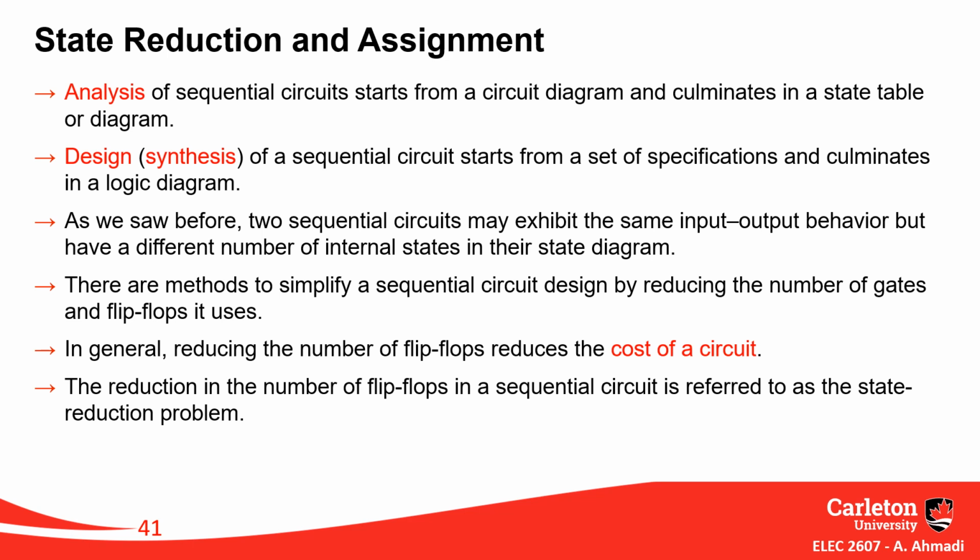Cost might be the speed or latency you need for your circuit. It can be number of components. It can be defined as power consumption of your circuit. It can be defined as the silicon area your circuit needs. So be careful with the concept of cost, right? But in this class, we refer to the number of gates as cost. However, next year in more advanced courses, you see a deeper concept of the implementation cost.